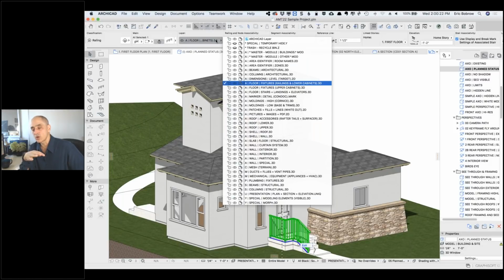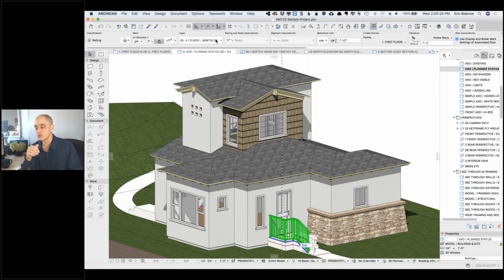If you want to show just a partition plan, just where the walls are, you would turn them off. If you want to show fixtures, things that are fixed in the building, not furniture, then they both come on. But given how rich the railing tool is and that it has a different function, maybe I should break that up into two different layers for railings and lower cabinets. Let me know what your thoughts are.